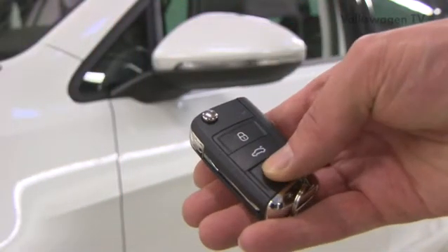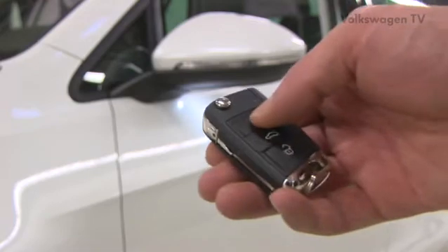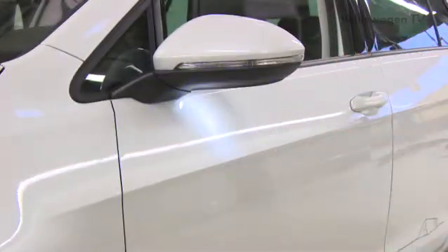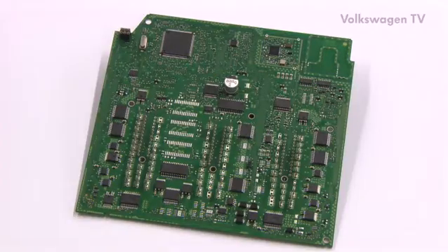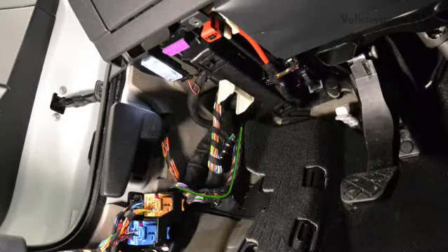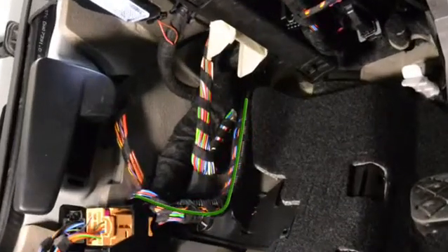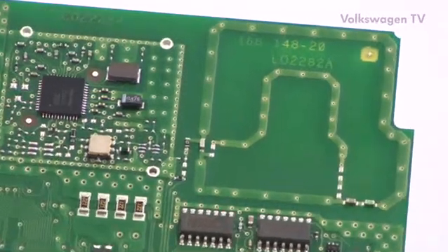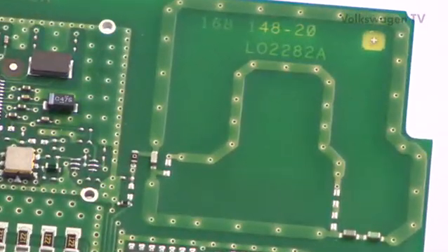Using a radio transmitter, the vehicle can be locked and unlocked without using a key. This is integrated into the remote control. When the locking button is pushed, the key sends a signal to the onboard supply control unit. The receiving aerial for the onboard supply control device can be designed as a cable antenna by means of a discrete wire. It may also be a part of the onboard supply control unit.